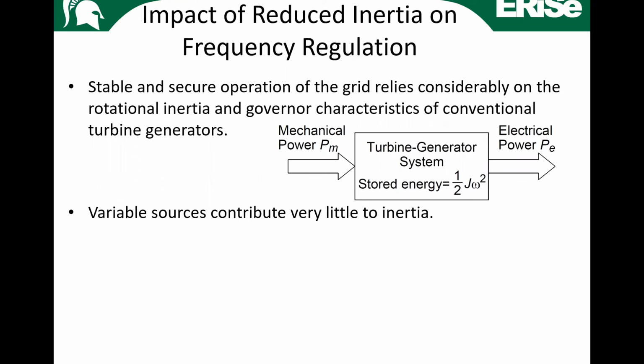Okay, now what happens is you have mechanical power going into the turbine from combustion of gases in a combustion turbine, steam going through the turbine in a thermal steam generator, and so on. So that's the PM, the mechanical power that goes in. And though you can control this, it is not instantaneous control. It takes some time to respond, okay?